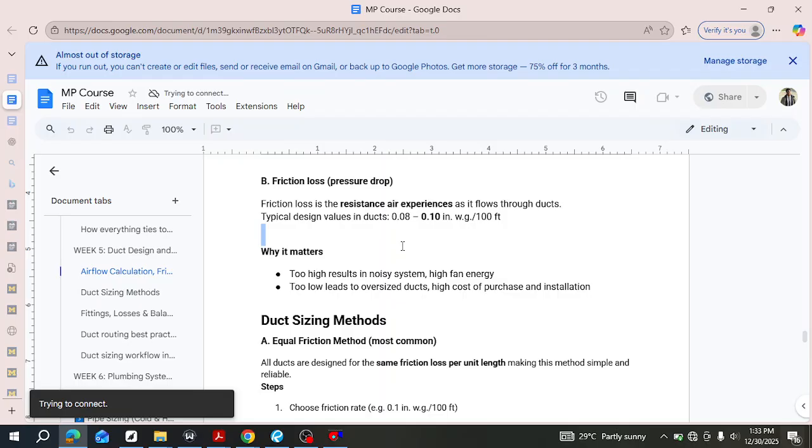So okay, in that case, square is usually just perfect, right? Some people select circular ducts because they want to improve the aesthetics, especially where the design doesn't work with a ceiling, and you have exposed ducts suspended under the roof, maybe in a commercial building like a mall, a place where they have to interact with customers or clients.